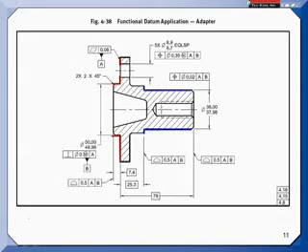That tap has a lot of cutters on it, and those cutters are kind of like a 900-pound gorilla. They're going to go where they want to go, and so I have seen a lot of eccentricity between the pitch diameter axis and the minimum diameter axis on a hole that's had a thread cut in it.